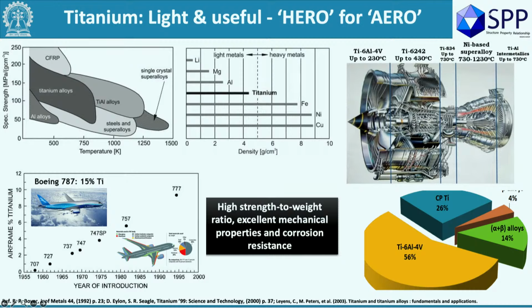The properties are so well balanced, and certification particularly is very, very difficult. If you search the web, the most papers on titanium are about improving properties with respect to Ti-64. So how to make this one alloy better, that's mostly what it is, because titanium goes into very critical parts in jet engines, and its specific properties are very good.